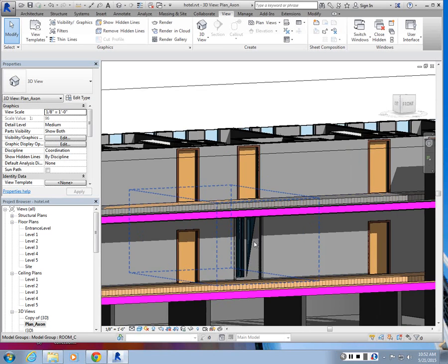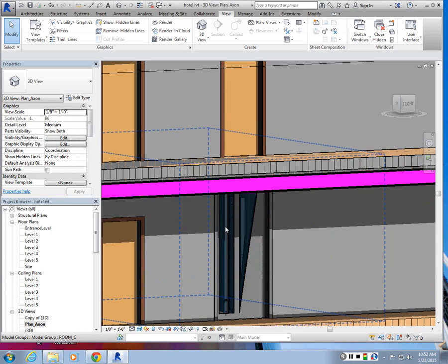You have to have something. You could also do a division here and do like a window on top and a door at the bottom. You could also model something like that, right? It's the same with doing the extrusion family. You just create another reference plane there for the top window, and then put the door frame at the bottom, and then model the window on top. Like a train cell? Yeah, you can do that too. I'm just making a single door.